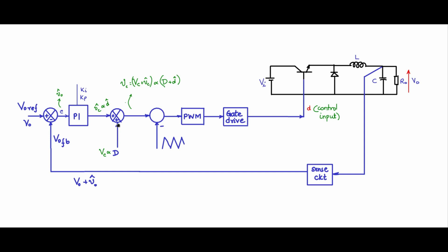This handles the steady state part, and any deviations, any disturbance, PI takes care of, handling only small signal deviations. Therefore this PI will be very robust and very fast because the deviations are small. In this way you can introduce the feed forward term and make the controller fast and reliable.